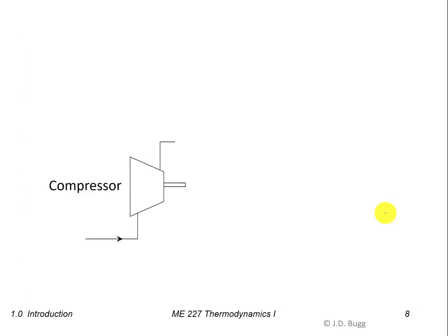We want to look at another thermodynamic cycle that has many similarities with the one that we just looked at. Going to change a couple of things though. The working fluid in this particular cycle, rather than being water, is going to be air. That will be the first change. Now we're going to go through many of the same processes, but not quite all the same. The first one, however, is going to be the same. So we're going to take some air here at the inlet to this thing, and this air is just going to be standard conditions. So 20 degrees C and 1 atmosphere essentially. So normal air. Now we take it and we want to pressurize that air.